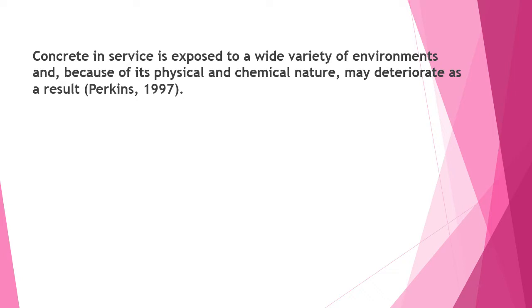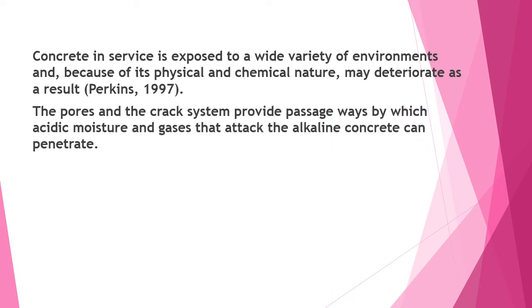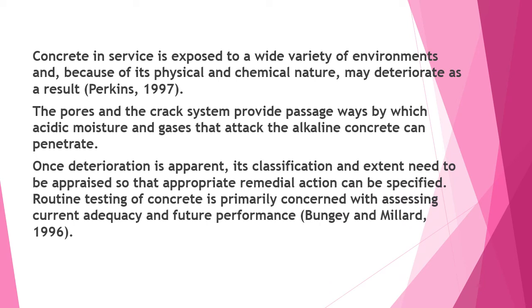Concrete in service is exposed to a wide variety of environments, and because of its physical and chemical nature may deteriorate as a result, as stated by Perkins in 1997. The pores and crack system provide passageways by which acidic moisture and gases that attack the alkaline concrete can penetrate. Once the deterioration is apparent, its classification and extent need to be examined and remedial action has to be specified.